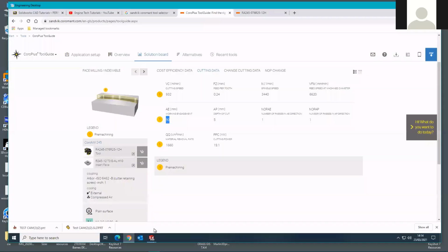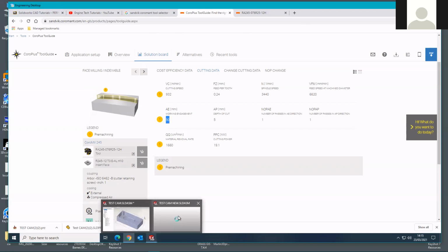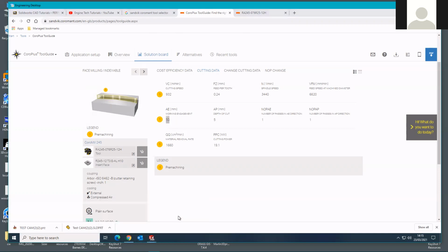Should it be 50%, which I think was the recommendation there? So that's 50 millimeters, from I think around an 80 millimeter diameter tool. So that is quite large engagement. There's not much of the tool that's not engaged in actually cutting slices. But anyway, that's a good reference to populate some of that cutting data.